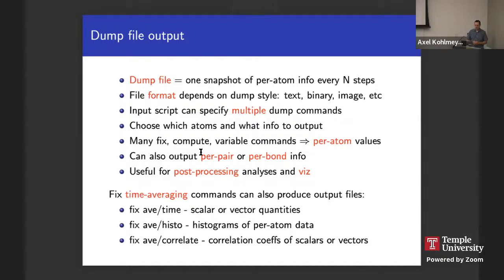Okay, and then there are also some other fix commands that do time averaging and compute and can produce output files. So there's fix ave/time, which can output either scalar or vector quantities. You can create a histogram, and you can also produce correlation coefficients for scalars and vectors.